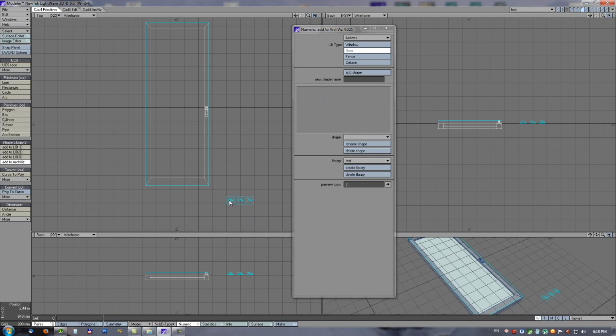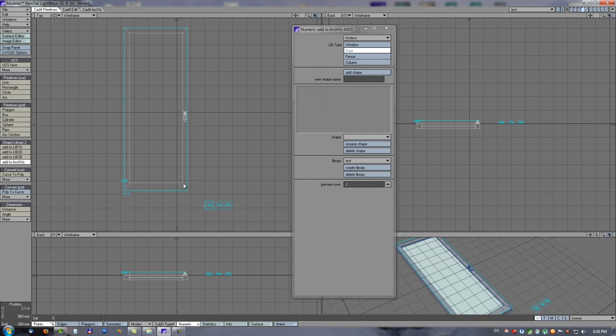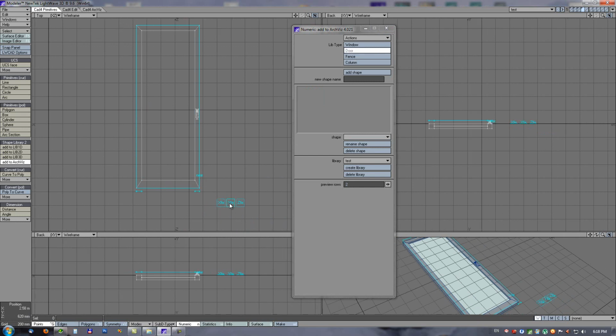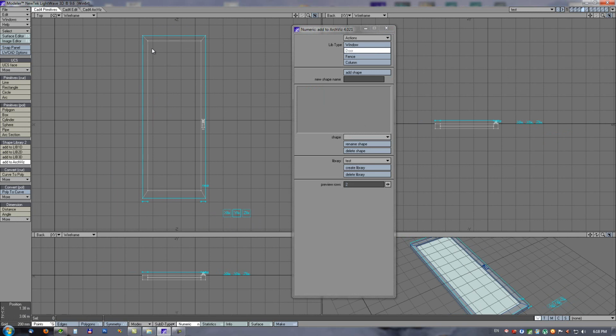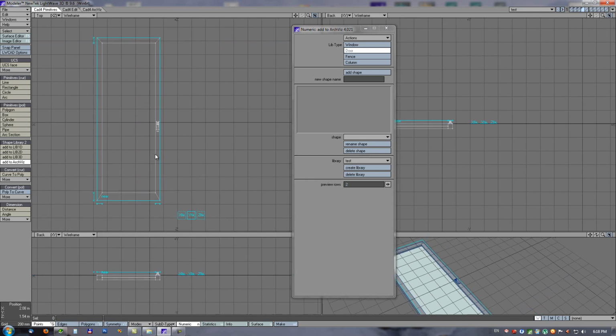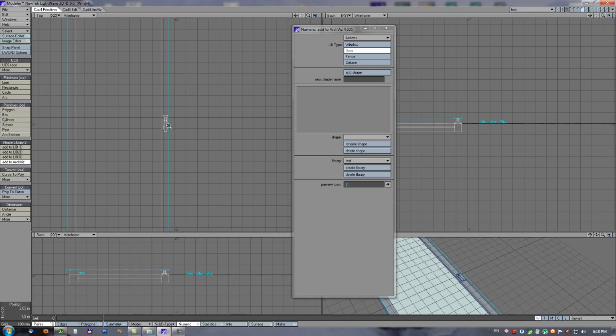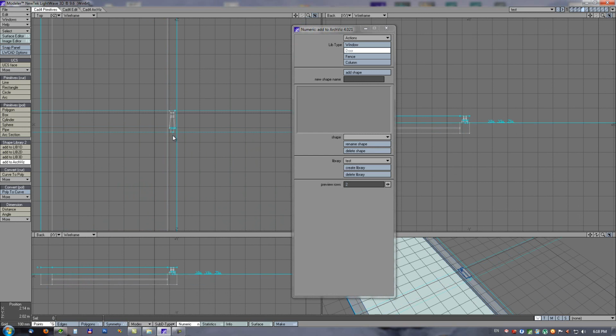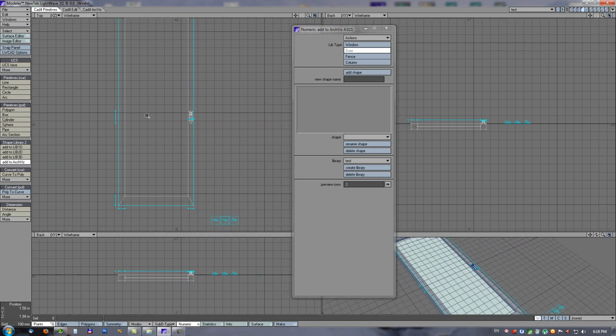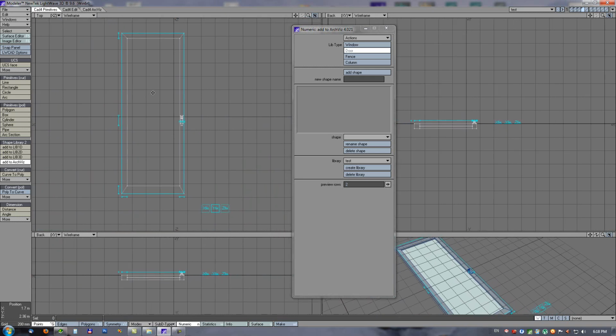So first I click the X fix button, and now I will set which interval should be fixed. Same for the Y axis. Here top frame, bottom frame, and also I want this handle to be fixed. I don't want to stretch it when using it with the window tool.